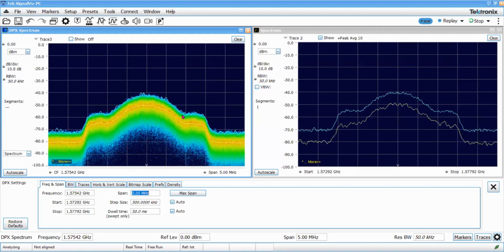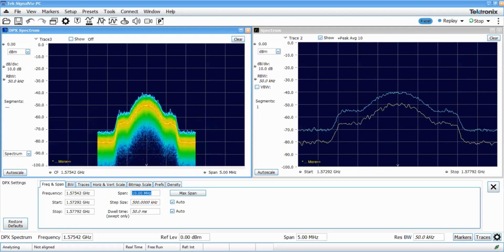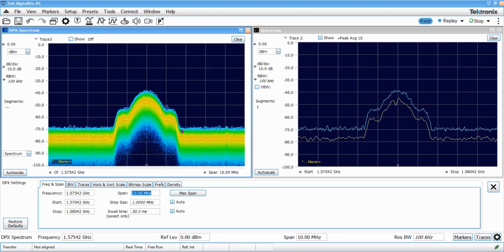So you need probably at least 4 megahertz of bandwidth in the receiver so that you can cover from here to here. This will cover maybe more than 99% of the power transmitted by the antenna to your receiver. The wider the bandwidth, the better. But if the bandwidth is too wide, you also get other noise that you can see here. So I made it 10 megahertz. All these noises will also enter, but the receiver will again do some filtering. So it may not be a problem, but it depends on the design.